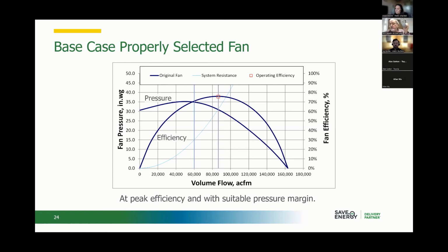That's when you start getting into a whole bunch of application issues. If you were to use the more efficient fan for a furnace, that furnace would have to be about double the size of what it is right now. So you start running into those kinds of considerations and application issues that make this determination of one for another. A little bit of thoughts that also address questions of fan selections and what kind of fans you have out there.